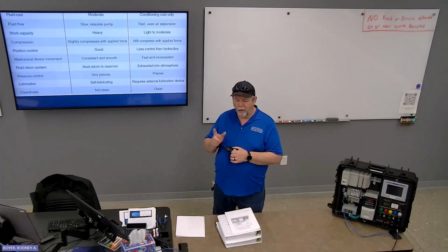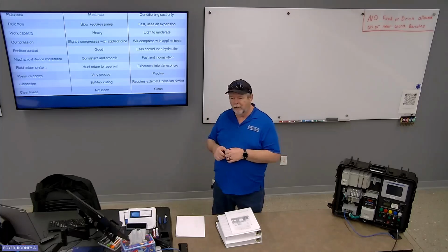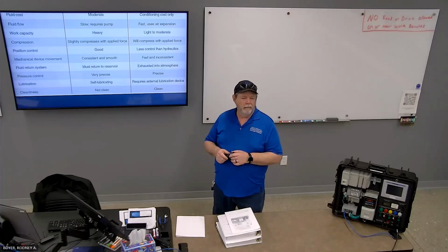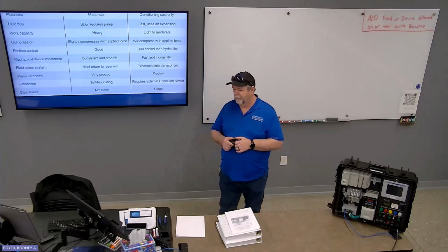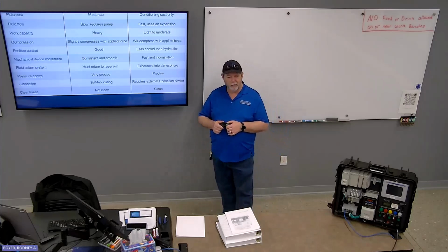Then one drip every minute, every 30 seconds, 5 minutes, whatever that number is, and you'll be able to see it. You need like one drip every 24 hours. So who's going to sit around and wait for 24 hours to see it drip? I'm thinking a grand total of nobody. So you can bet that your pneumatic system's got too much oil in it.